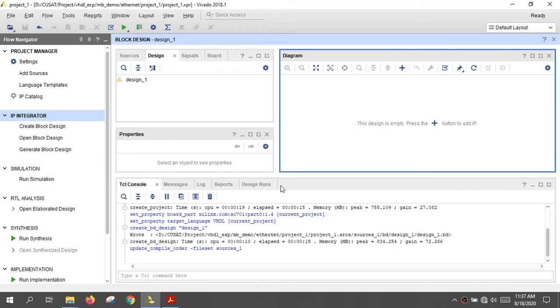We can create some amount of RAM within the FPGA itself. As we have seen, we can configure a maximum of 128K of RAM using the block RAM cells available in the FPGA itself. And in the previous demo, we have executed our application program from that local RAM itself within the FPGA. So we were not having any external memory.